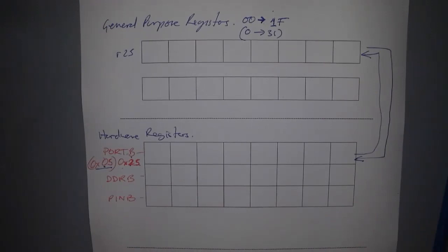And there's a very similar process here. This is an interesting little thing here about compilers for some of you to follow. Now what happens here is we take our value of port B, we stick it into R25. So we grab our port B value. Then what we do is we take our value that's in R24 and we add it to the value that's in R24. This is the shift left operation.